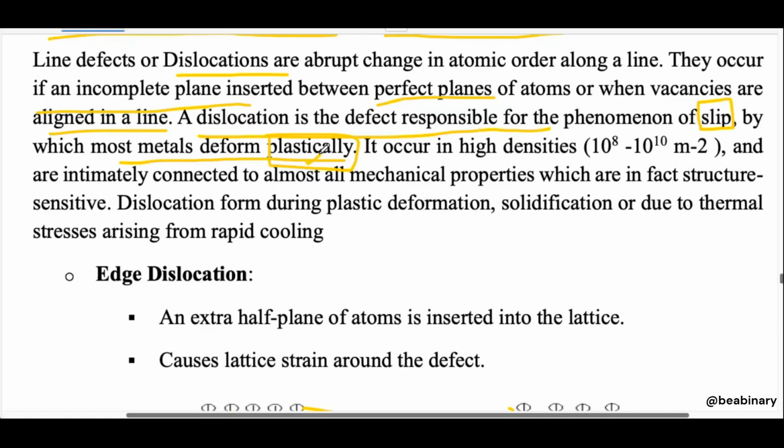So it depends on your priority, on your application. Most of the time, if you talk about engineering applications, like if you have made any kind of equipment, or a structure, building or bridge, we cannot bear the plastic deformation. There could be an elastic deformation that would be tolerable, we can tolerate that. But the plastic deformation, that we cannot tolerate. But in machining or in a production part, we are basically concerned about the plastic deformation, so that we can get the desirable product.